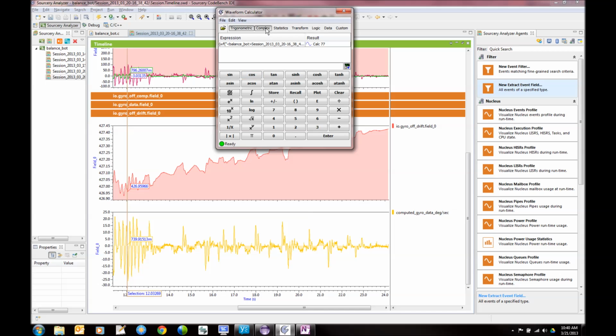If you are able to log a complex array of trace data, an example could be a time domain frequency sweep that's being done in software to assess the closed loop stability of a system. In such scenarios, we could generate Bode plots and measure the gain and phase margins using these complex functions provided here. We have a statistical palette which allows for generation of histograms. We have fast Fourier transforms, inverse fast Fourier transforms, and various transformation functions available to us as well.